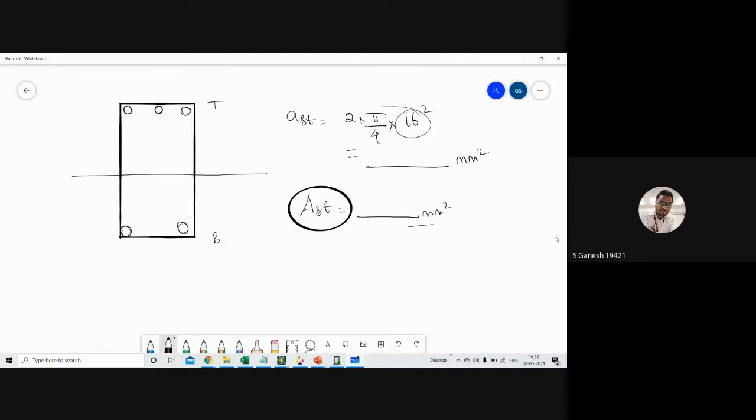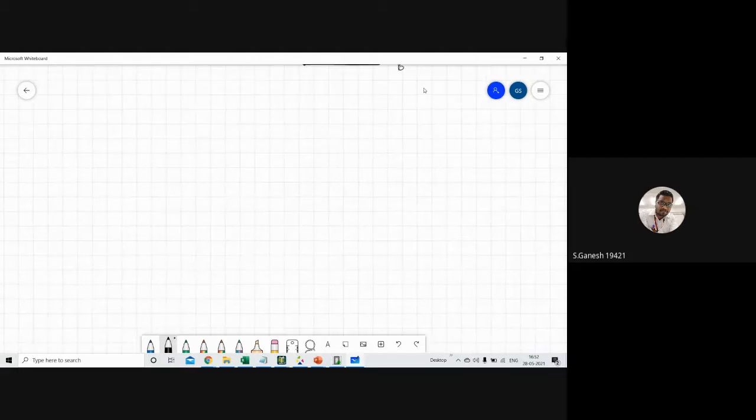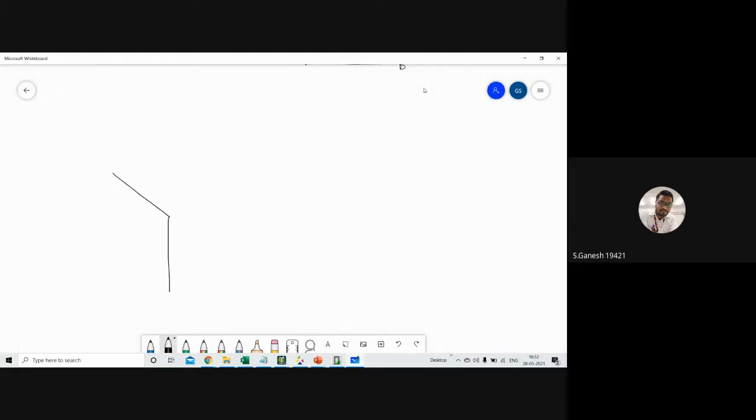The second layer is here. This is called the second layer. So top, second layer, bottom, single layer. So these are your rebars. Now, the bottom can also have 2 layers, suppose, in heavy sections with heavy reinforcement. So you have second layers at the bottom also. So when you project this in 3D, what happens? This is how you project it in 3D.